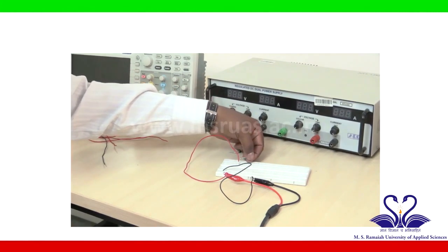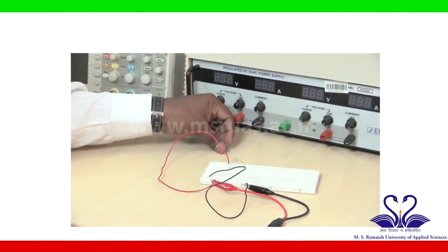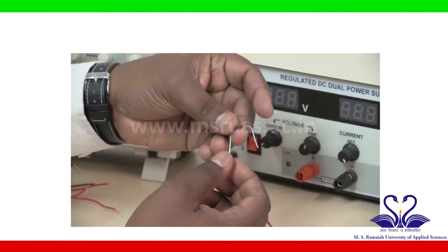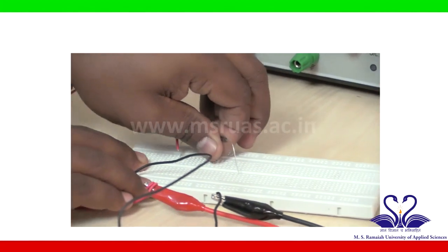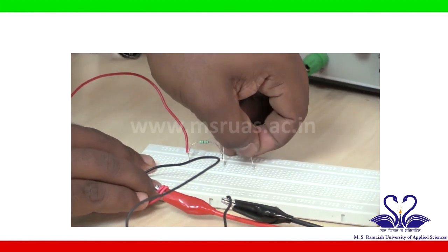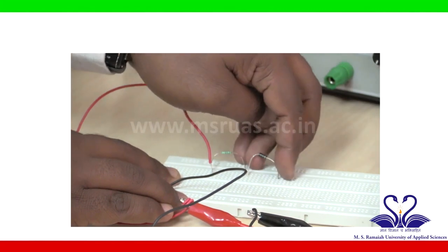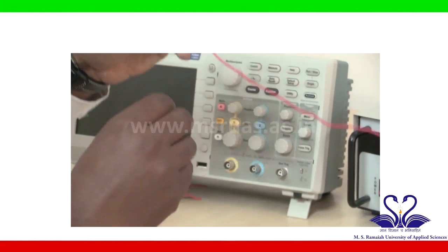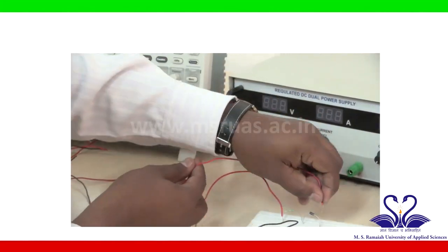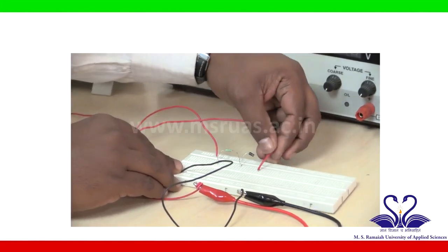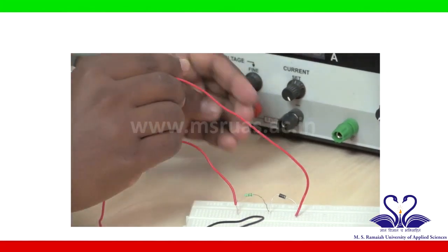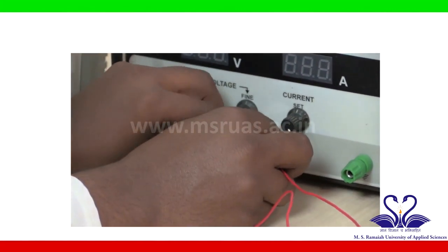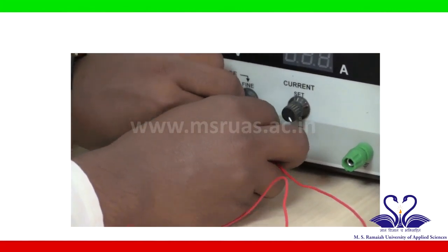Now, the resistor's other end is connected to the diode P terminal. This is a diode, this is the P terminal of the diode. I will connect the P terminal of the diode to the resistor, and the N terminal of the diode is connected to the positive terminal of a DC supply. So, I will take one wire and connect it to the negative terminal of the diode. This negative terminal of the diode is connected to the positive terminal of a DC voltage source.